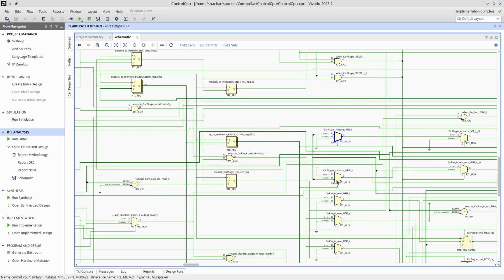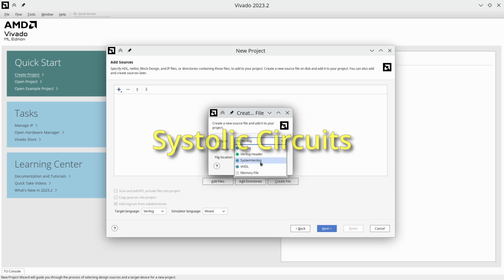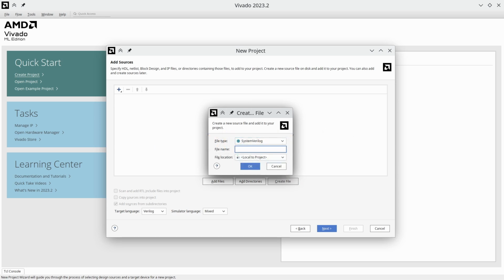This is a sequence of combinational circuits that are fed from flip-flops latching the value of other combinational circuits. As the clock arrives, the intermediate results are latched and the next phase logic takes place. This phased advance of the data through the circuit reminded someone of the way a heart beats, hence the name, systolic circuits.